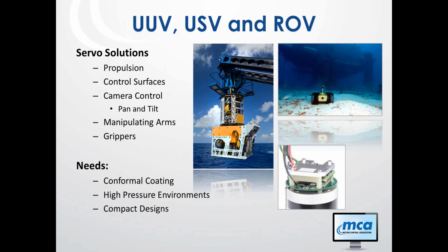Again, you're looking at very compact designs. There's not a lot of room in these bots that go very deep in the water. So much of the chassis is designed to deal with the pressure, so you don't have a lot of room to put in these other components. What I show on the picture on the right are a couple examples of these bots, and then a picture where the drive is sitting on the motor in the back end housing of the motor, and that whole motor electronics is sitting in a bath of oil, non-compressible fluid, so they can go to very deep ocean levels and deal with those pressures so your components aren't going to be crushed in the pressure.